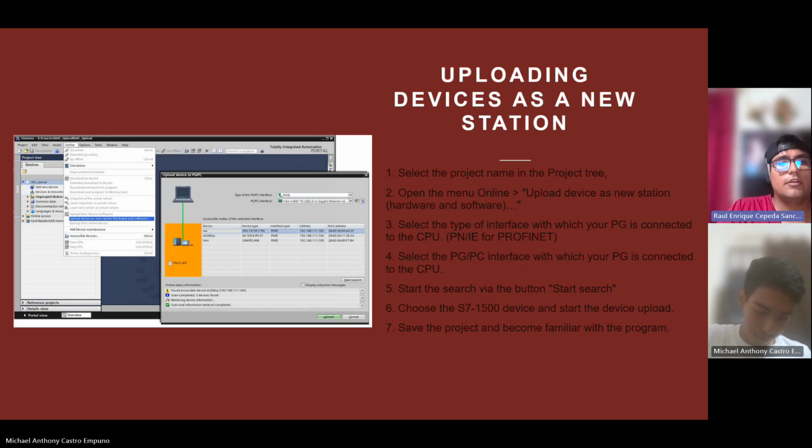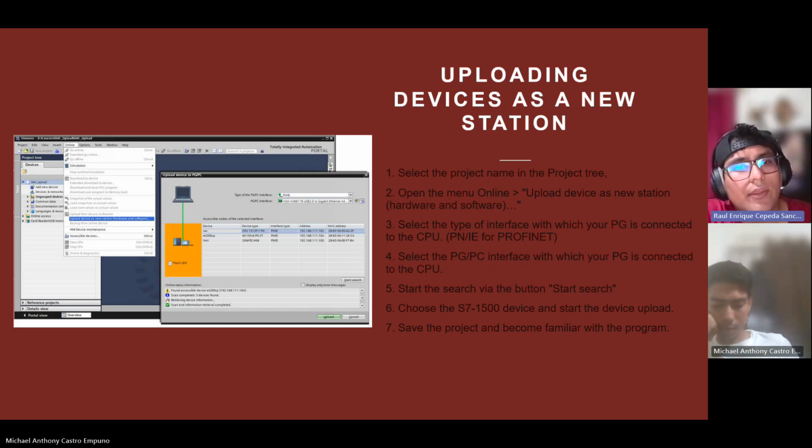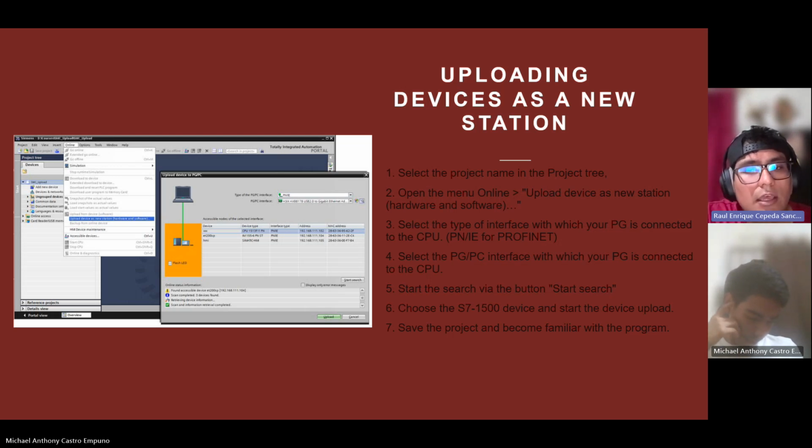Migration of STEP 7 projects. With the hardware, the hardware configuration can also be migrated. Otherwise, only the software can be migrated and must be adjusted to the supported hardware. To check whether the hardware is supported by TIA Portal, it is possible to check this in advance. For this, you can use the readiness check tool, which is available for download on the support page.